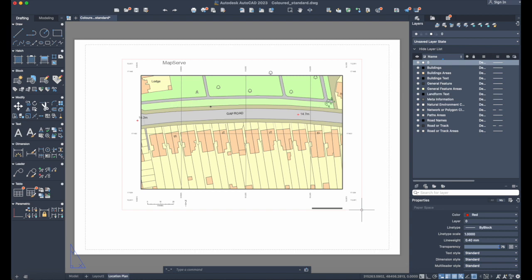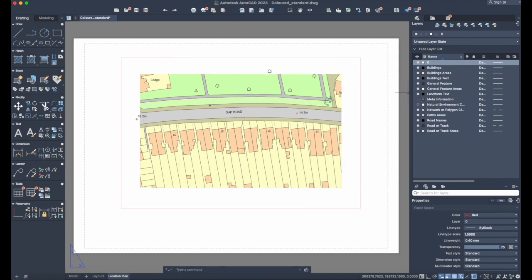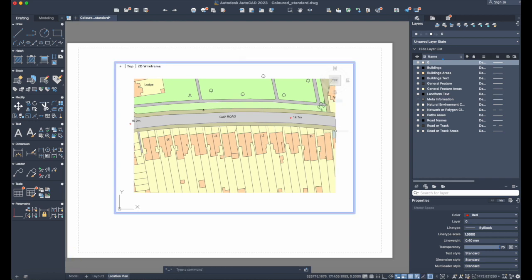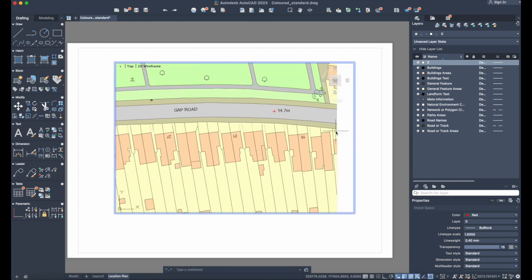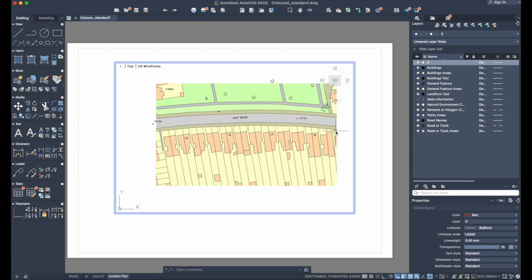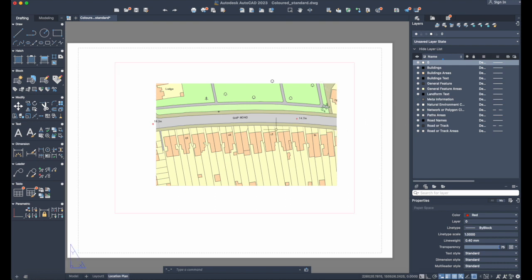So at paper space, you can now change the extent of how that map should sit on the page, whereas if you click within that, you're back in the model space where it acts as it did previously at this model tab here. And this allows us to zoom and pan as you see. By double-clicking on the gray, we then revert back to the paper space.